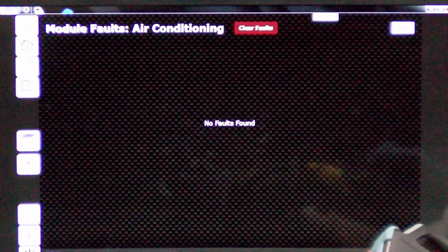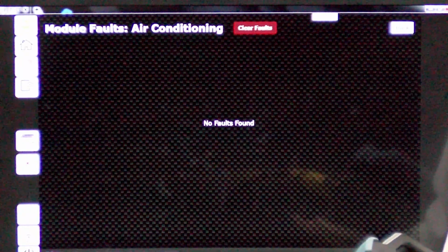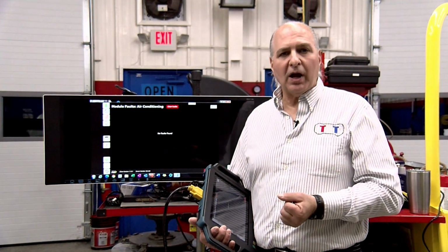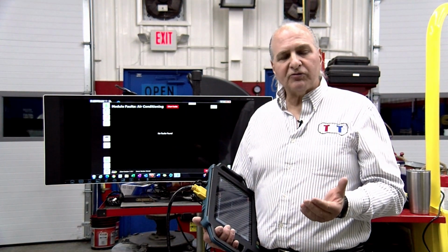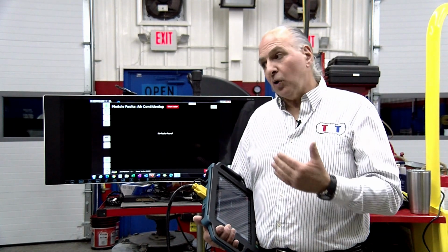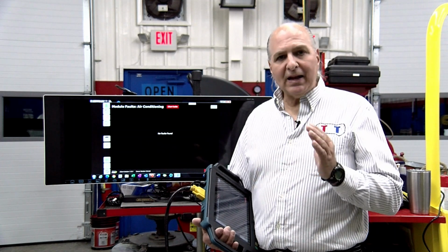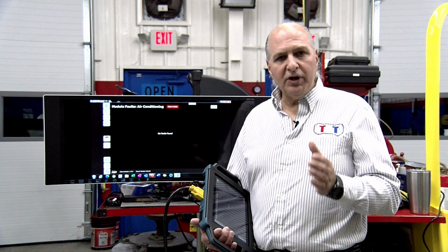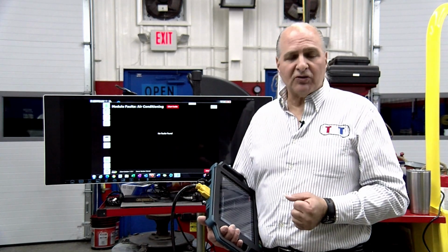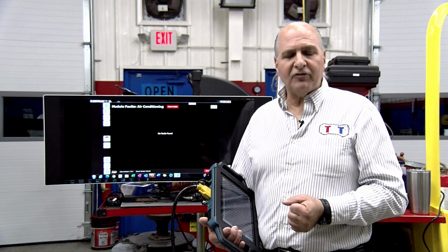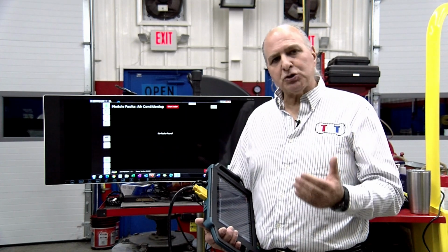And what do I mean by the right stuff? This car takes 134A, right? And most of you have a 134A machine. Newer vehicles, of course, are R1234YF. But when we're talking about a hybrid, we cannot use PAG oil. PAG oil that you used in all the other cars that you're servicing with 134A and in some 1234YF vehicles, you need a special oil.